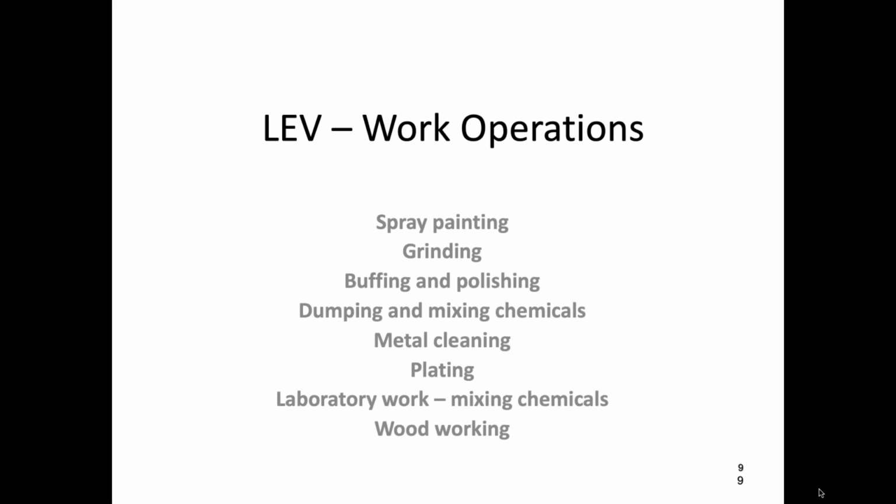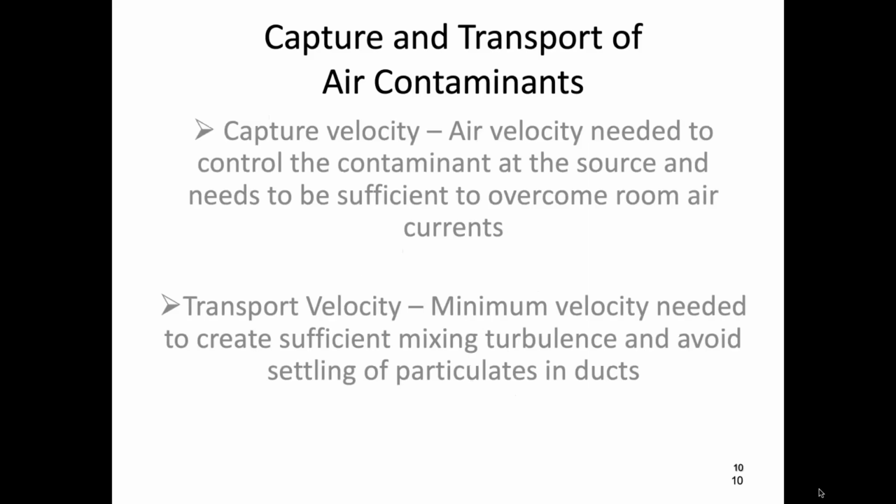Those all have hot baths. Some of them have solvents in them that you want to control. Laboratory work. Yes. So the hood captures the particle. Exactly. The hood captures all of the material, or as much of the material as possible, so it doesn't get into the space and doesn't get into the breathing zone of the worker.